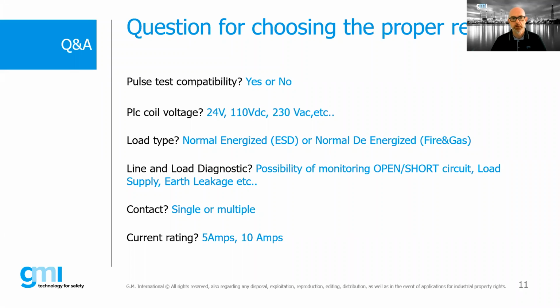Furthermore, let's not forget that the choice must also be made bearing in mind the need for diagnostic capabilities on the part of our relay, the need for single contacts or multiple contacts, and finally the contact rating of the relay. Even in the latter case, the choice is important, as choosing an incorrect contact rating can have serious consequences for the state of health of the relay and therefore of the entire application.